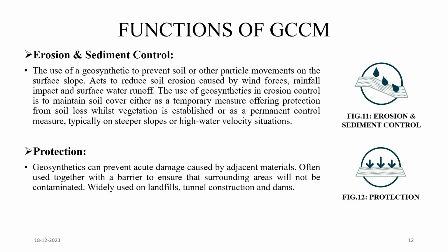Fourth function, soil and sediment control. The use of geosynthetic to prevent soil and other particle movement on the surface slope acts to reduce soil erosion caused by wind forces, rainfall impact, and other water runoff.